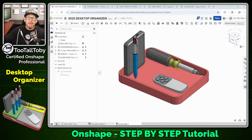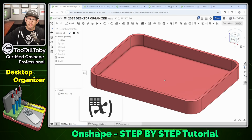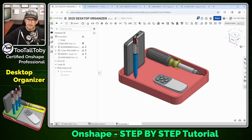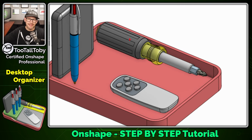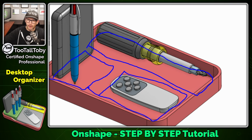All right, so now we've got 3 tabs down at the bottom here. We've got the main red tray, we've got the variable studio, and we've got our assembly. And the next thing we're going to do is start adding in the actual blocks, doing the in-context design. That's really going to be kind of the meat and potatoes of this video. However, before we get started with that, I just want to go back into the variable studio and add in some variables.